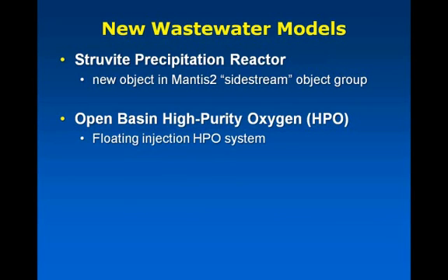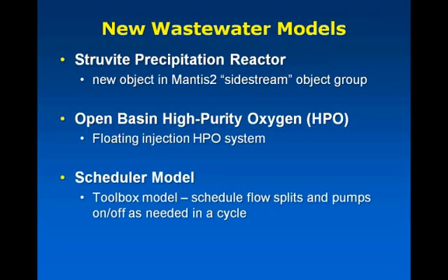We have a new HPO object. So as you may recall, we've had for some time a closed high purity oxygen system, so an open activated sludge tank with a headspace and a closed lid on it. We now have created one that's the same thing, high purity oxygen, but it is an open system. So it's a floating injection where the HPO gas feed is being injected and mixed directly down into the liquid.